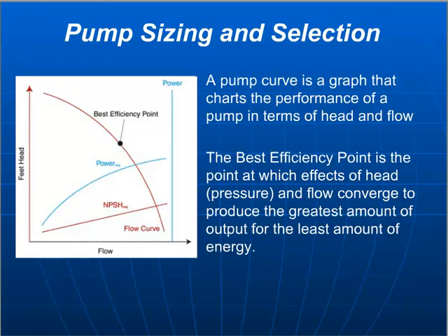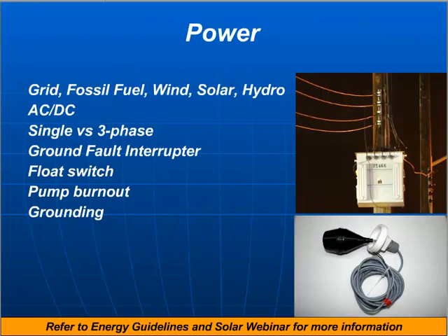And you're just going to have to go from there with your different pump options. This is just a slide of a pump curve to show you what you should expect to see from a pump manufacturer, so that you can make sure that for the specific flow and head requirements you need, based on the elevation and the flow demand of your community, you're picking a pump that meets that with the best efficiency possible. Any pump has these pump curves, and that should be something you're looking for and will eventually have to be a part of your design.